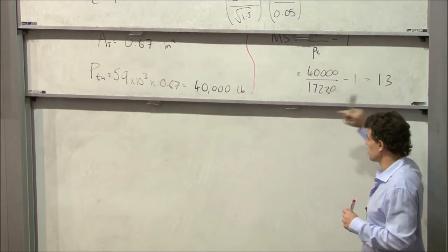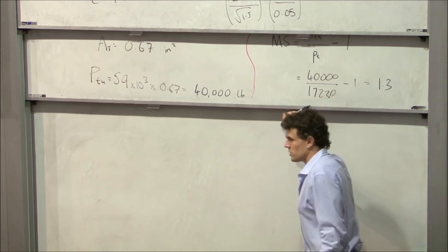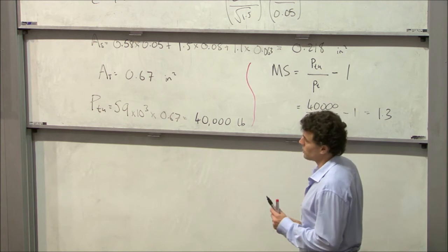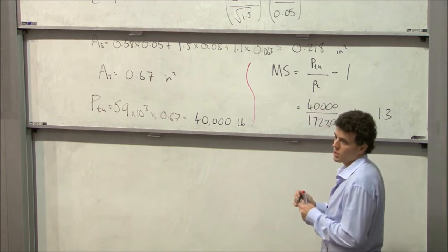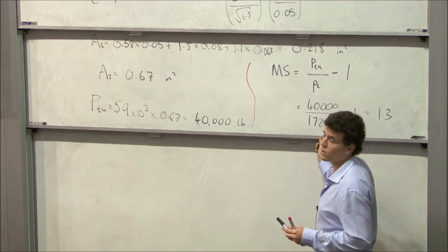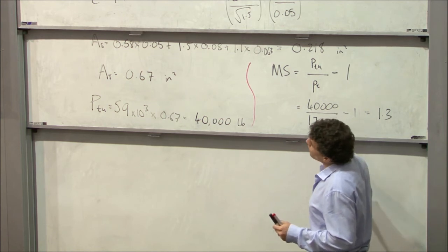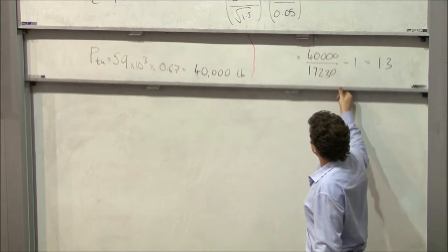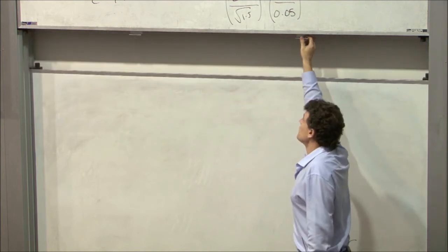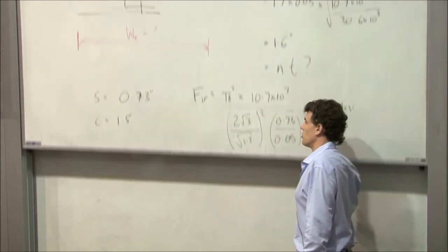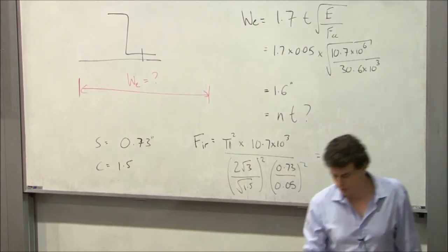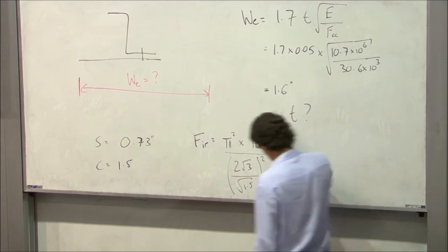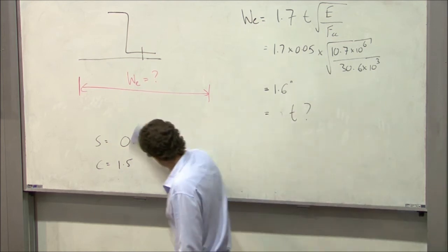The reason is because it's thin-walled. Thin-walled structures are very good in tension, but they're not very good in compression. So the tension case is never going to be the critical case. Okay. Let's move on to crippling, which is this thing that I've been talking about for a while.